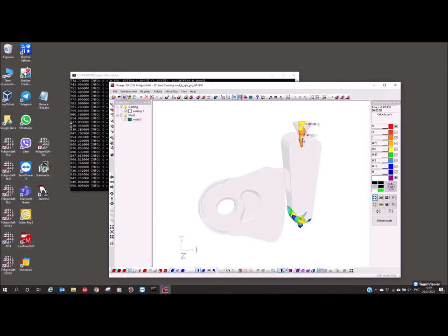everywhere, a lot of points, and with the right button, double click right button, I will turn off the points, and I can edit this scale. For example, my start velocity is 0.8, and I can make the maximum velocity here 1 meter per second, and these checkboxes fix the values here, and if I turn off